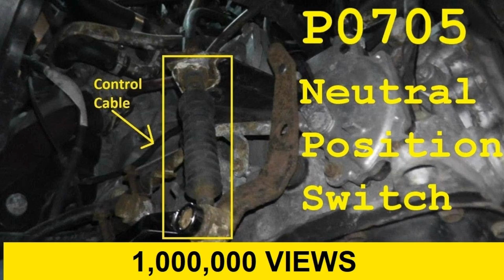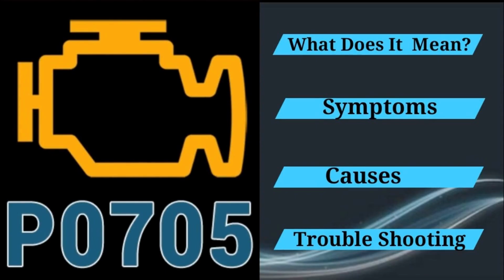There may be problems with engaging and disengaging the gears. Fluctuating speeds when changing gear. The transmission may lag in engagement. Increased fuel consumption. The severity of error P0705 varies from medium to severe. The engine may stop starting. The transmission may also go into emergency operation.